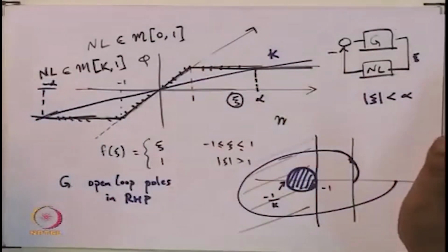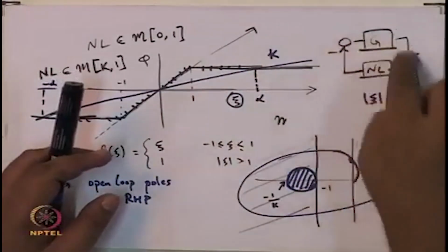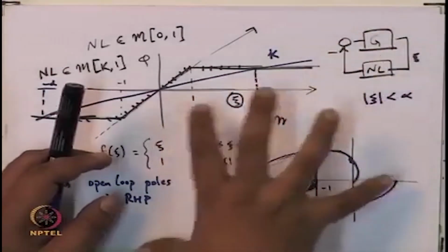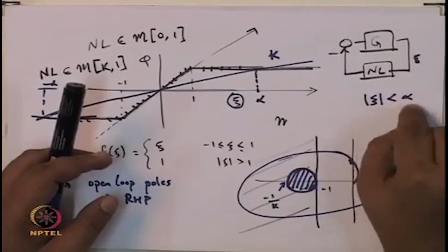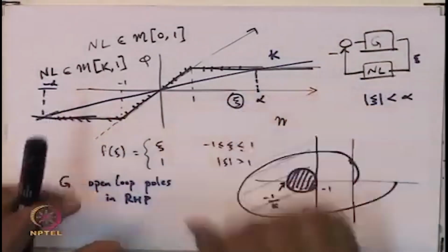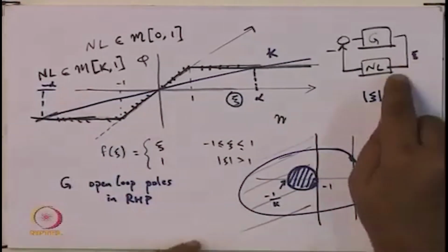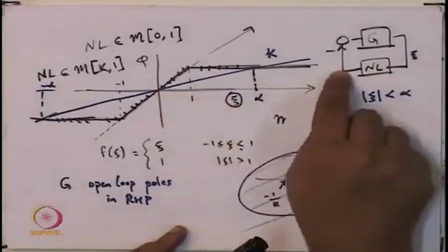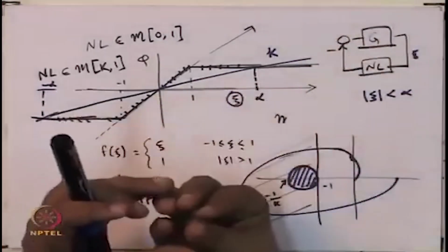So it's not globally asymptotically stable, but it's asymptotically stable so long as you look at only that portion of the phase space where the modulus value of psi is less than alpha. And for that restricted region of this phase space, of course this includes the situation when psi is equal to 0, and when psi is equal to 0 the output is also equal to 0, and that in fact is the equilibrium point that we want to get things into.